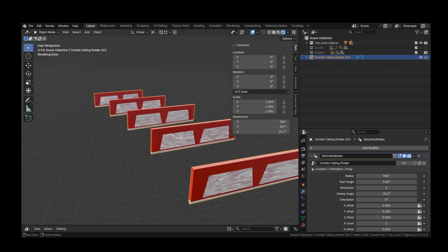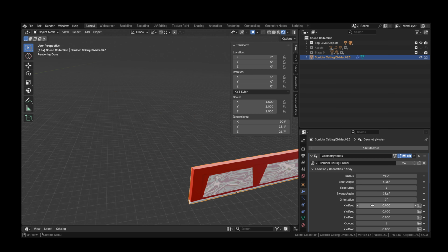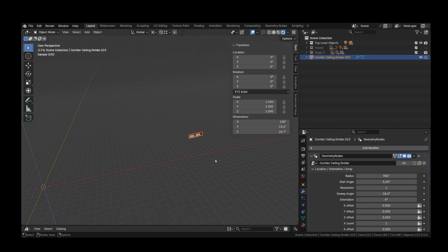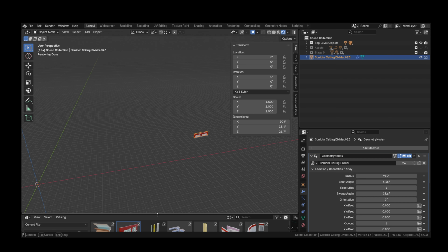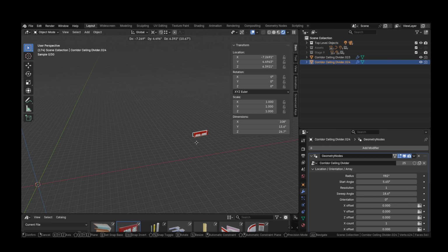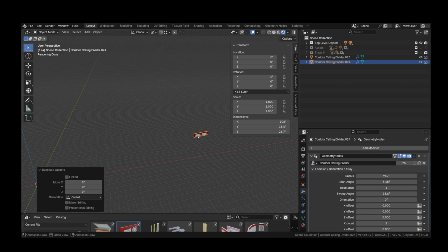So what I typically do there is not have an array. I will duplicate the asset with another keyboard shortcut I use quite often, instead of dragging another copy of that asset out here again, I'll just click Shift D on my keyboard. It creates a duplicate of that right away. And if I right click it, it drops it right on top of the original.